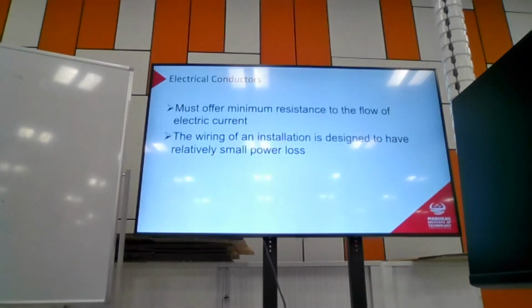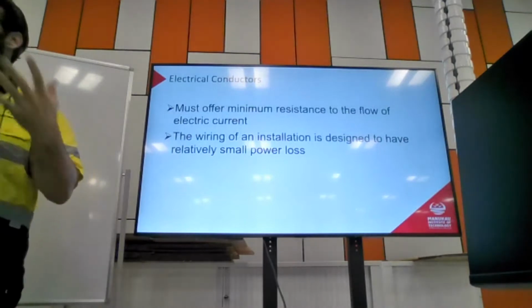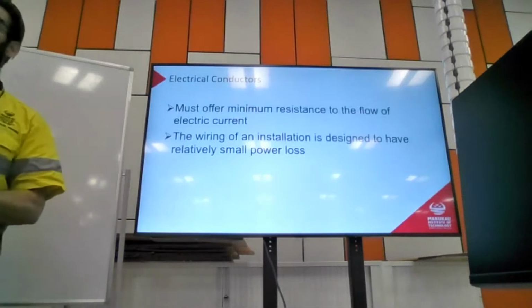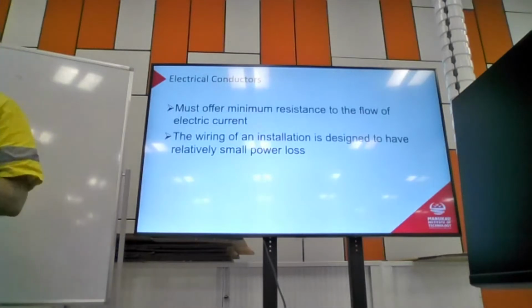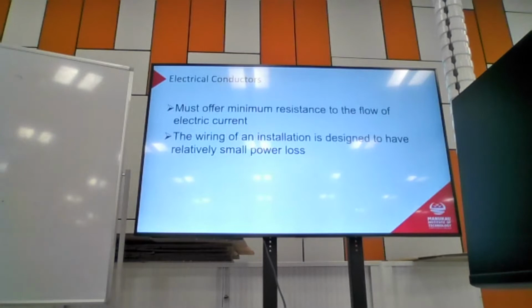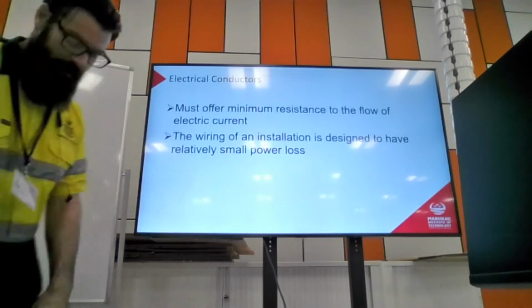Yes. The more resistance I have in a cable, the more heat is going to be produced, the more power will be burned and heat will be produced, so the hotter it will get. So the higher the resistance of my cable, the hotter it will run at any given current, unless it has a negative temperature coefficient. If it had a negative temperature coefficient, then the resistance will start to drop as we heat it up. So then the more current I put through it, the lower the resistance will be, and it'll be fine. But normal materials don't have a negative temperature coefficient.